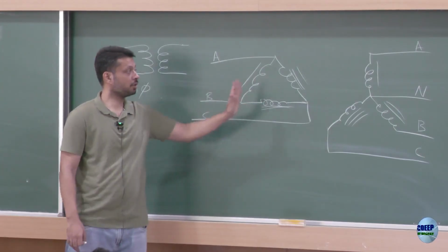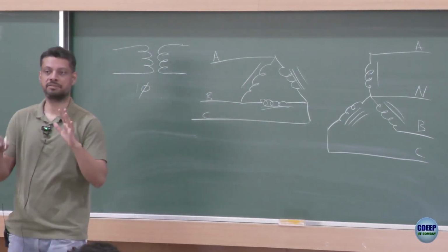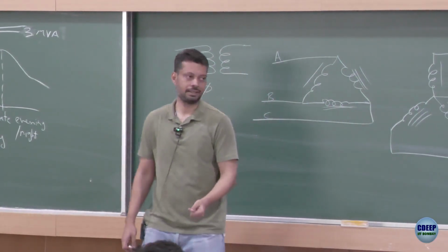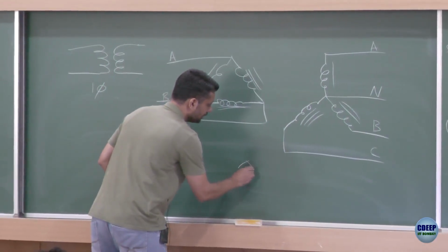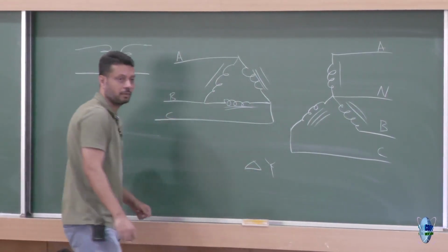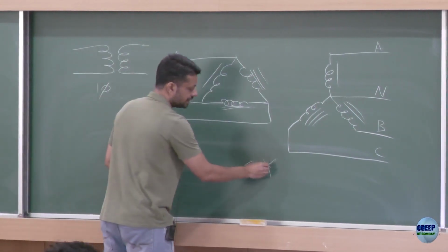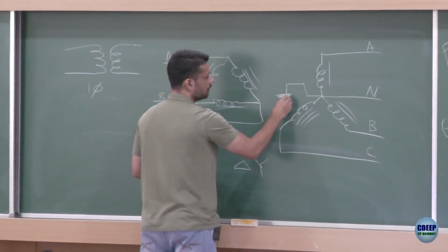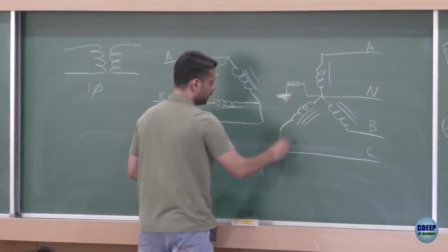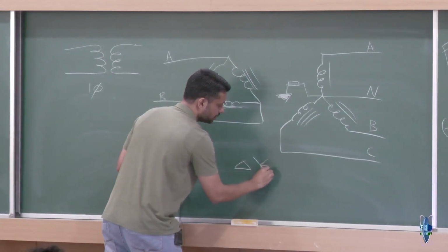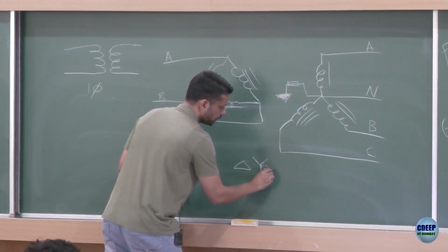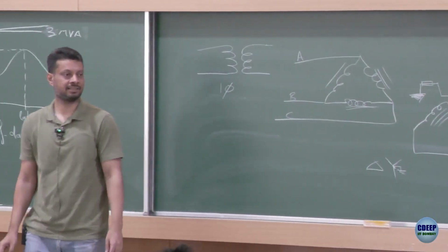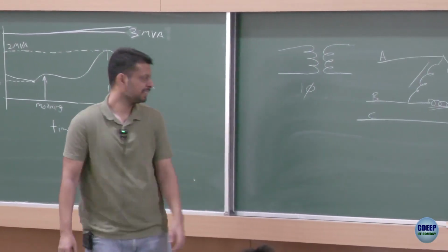In a 3 phase transformer you can have different arrangements. What is this particular arrangement called? Delta star. So, this is a delta star transformer. The star point is also earthed, either directly or through a resistance or an impedance, and this is how it is shown in the symbol. That means it's delta star with neutral point earthed.